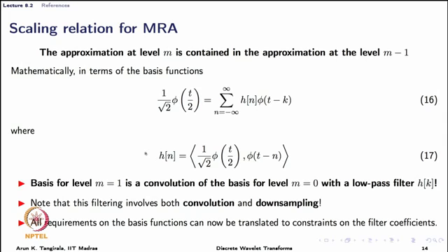But for now, what is important to remember is that these coefficients h are nothing but our low pass filter coefficients. Why are these low pass filter coefficients? Because as we go from V0 to V1, we are constructing another, coarser approximation, and approximations are always generated by low pass filters. So, the most important point is that instead of talking of phi of t, which becomes difficult later on, we shall talk in terms of these coefficients h. By specifying the low pass filter coefficients h, I would be indirectly specifying phi of t itself, and we will look at all of this in the next lecture.